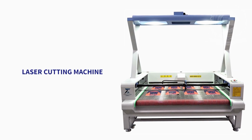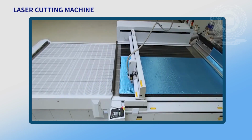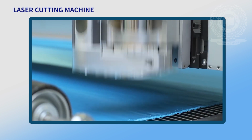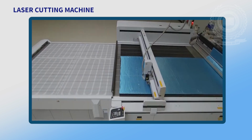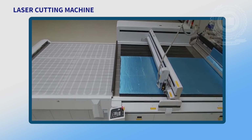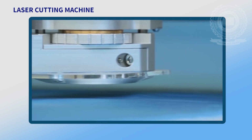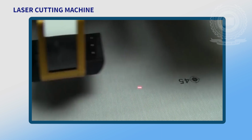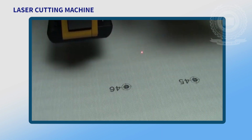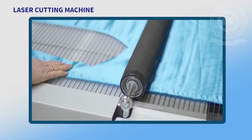Next is laser cutting machines. In this method, fabric is cut by a ray of light in a very fine spot using a laser. The radius of the spot of light is 0.25 mm and highly powerful. When the rays fall on the material, they generate heat on the material and cutting is done by vaporization. Fabric is cut at a speed of 13 meters per minute. The cutting head is controlled by computer.